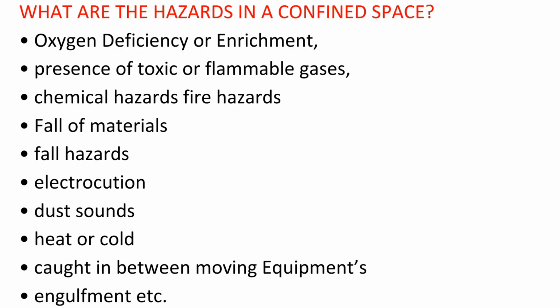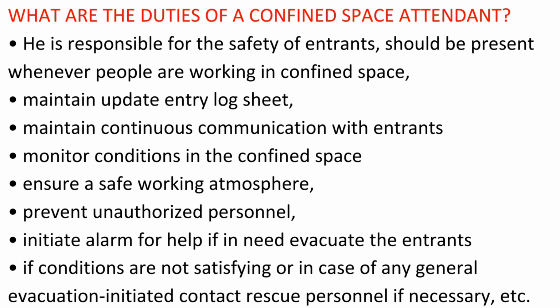Question: What are the hazards in a confined space? Answer: Oxygen deficiency or enrichment, presence of toxic or flammable gases, chemical hazards, fire hazards, fall of materials, fall hazards, electrocution, dust, sound, heat or cold, caught in between moving equipment, engulfment, etc.